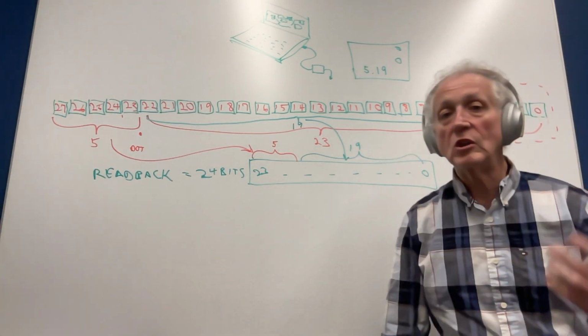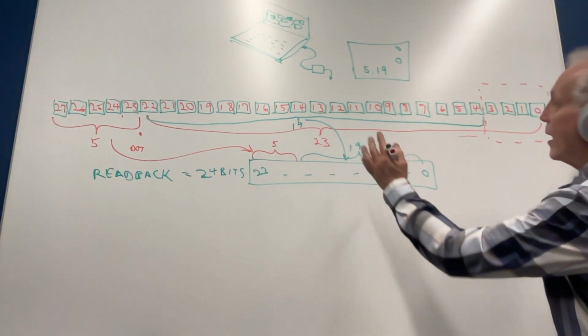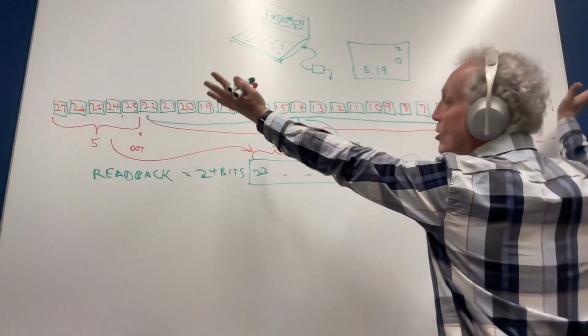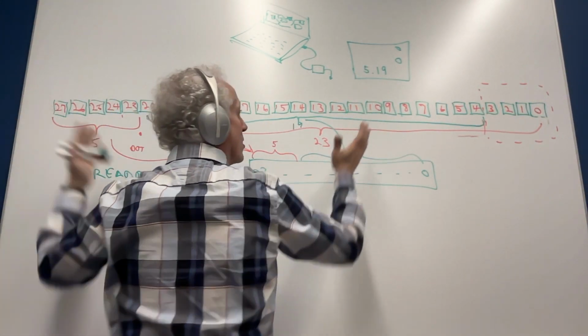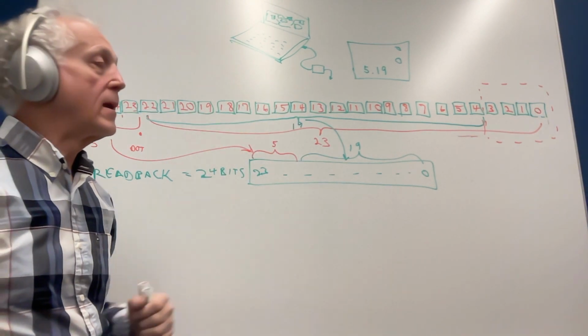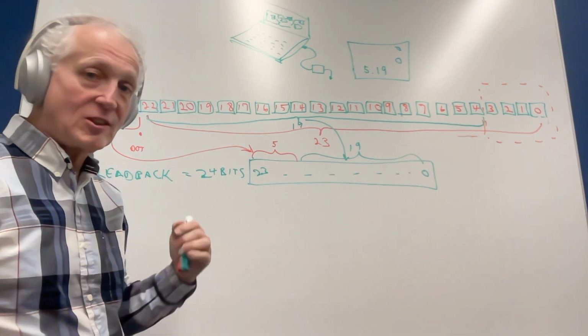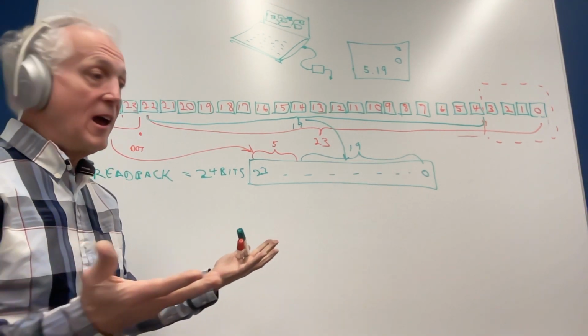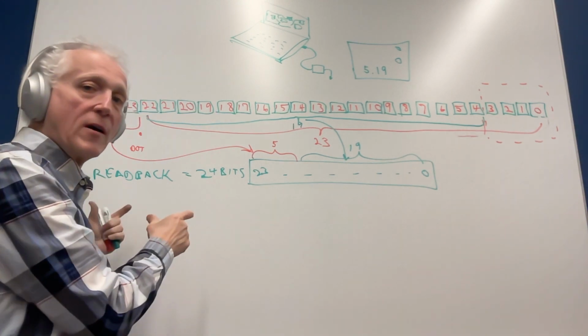So what we need to do is take this data in the core, the 28 bits, and shift it 4 bits over. So we need to do a data shift over. By the way, in the Sigma 300 core, we actually learned again, we improved. And there is an instruction in the core to do an arithmetic shift.